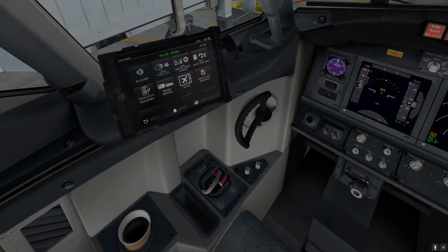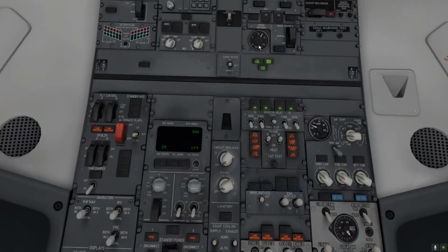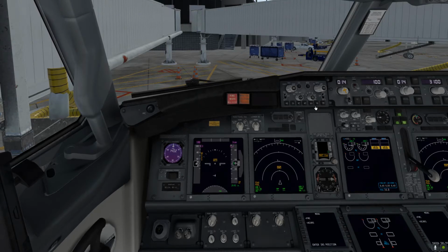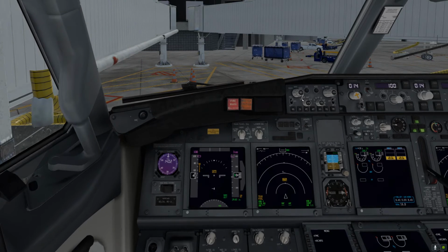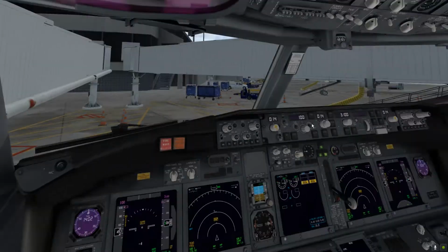Open the overhead and checking oxygen. Yeah, it's good, and as well we have good pressure up here in the bottle. And then we have a little bit of settings here. Altimeter now it's 2983. We have an expected acceleration of 800, so let's go up to 830 baro. Yeah, here we go. Flight path vector because I like it. Airport because I like it.